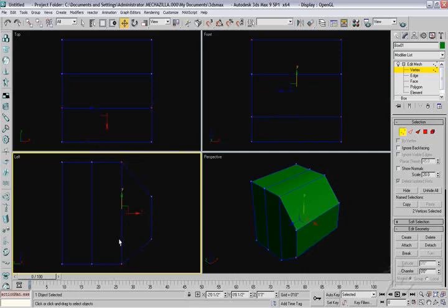upper and lower sections, and then switch to your scale tool, it will take a common point, because if you look up here under the main toolbar, you have a little button over here indicating where you want to scale from, or move from, or rotate from. And we have a common point. It's the second one. If you go ahead and click on that, so that it uses a common point between your selection here, we can go ahead and just grab the Y handle and use that to scale. So we can go ahead and pull that down. And so you've got something like that.